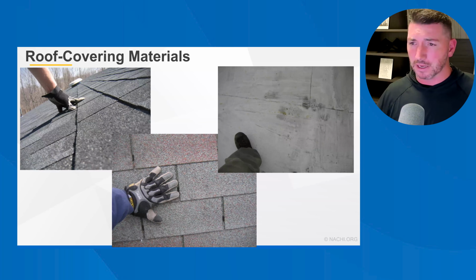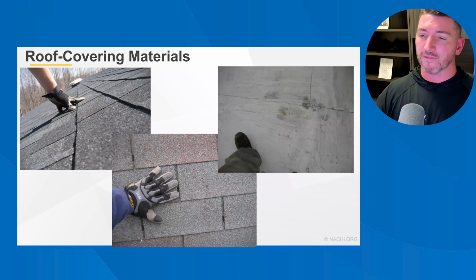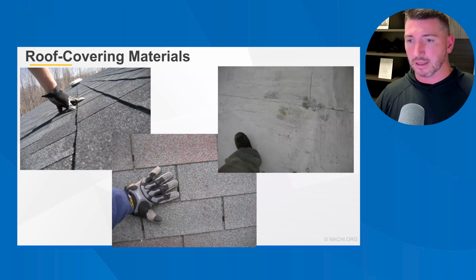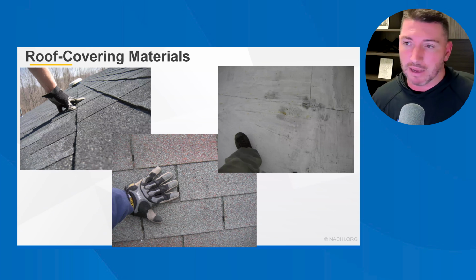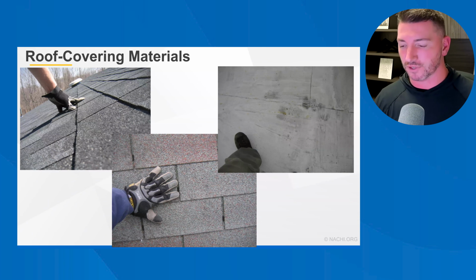And so that asphalt becomes the water shedding part of that membrane. They layer it over 2, 3, 4 times, and so you've got this big, thick built-up roof. And maybe they painted over it. A lot of times they'll do a reflective coating on those. They'll do mineral surfacing. They'll do aggregate. You'll have things where you can't actually see the surface of the roof covering material.